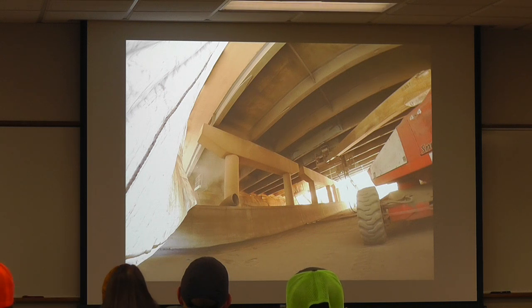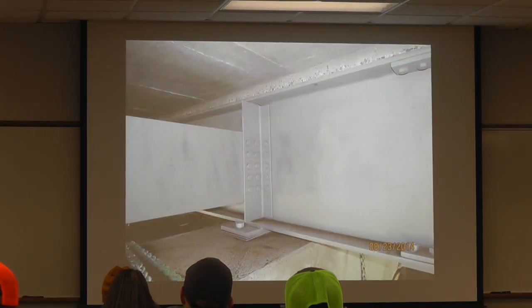Just another example of blasted and a little left over that they're still doing. This is a good example of near white. You will end up with what we call just little shadows. If it's never been repainted before, you may have mill scale. So you may not know what mill scale is.